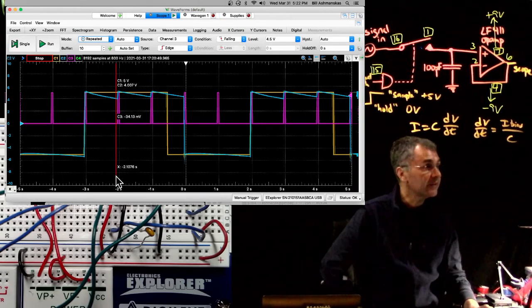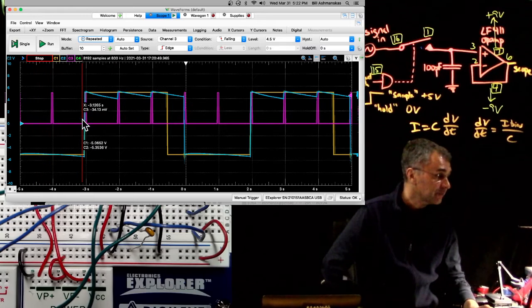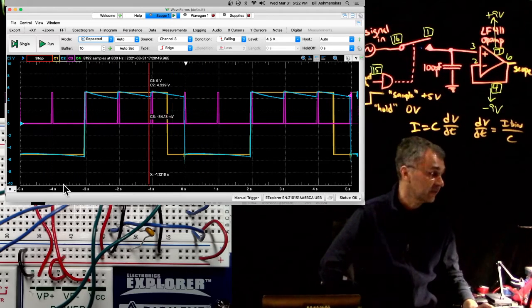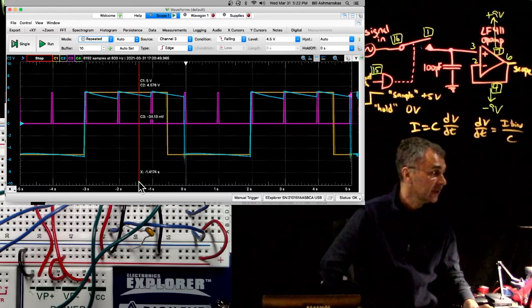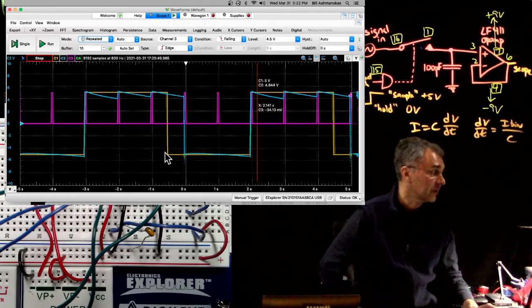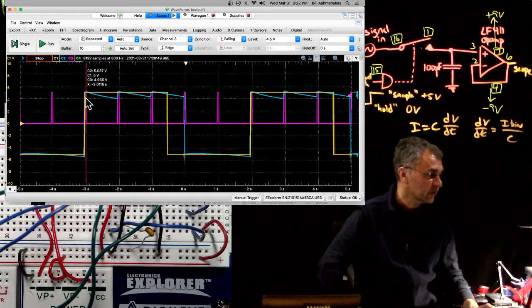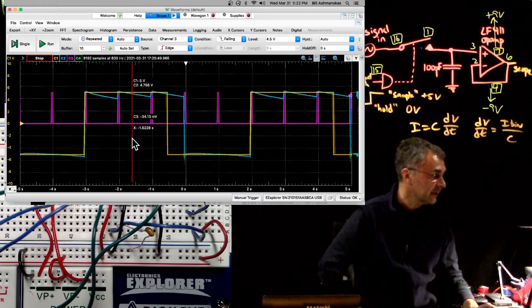So then I just captured one trace. The magenta, or violet magenta, is the go signal. The go signal comes once per second, so it's 1 second per box here. And then the yellow signal is what we're sampling. It's high for 2.5 seconds, it's low for 2.5 seconds. Right, it's minus 5 volts for 2.5 seconds, then plus 5 volts for 2.5 seconds, minus 5 volts for 2.5 seconds, and so on.